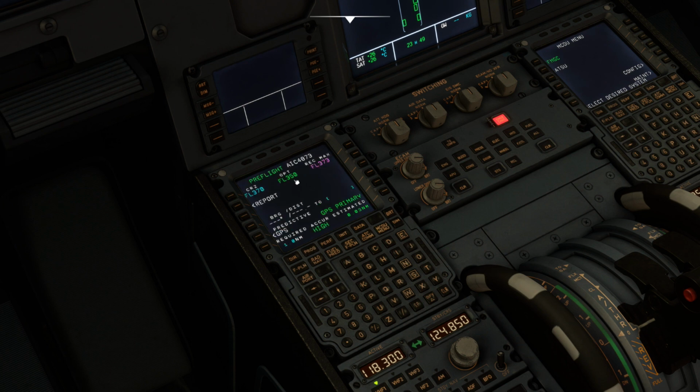Program, our optimum flight level is 350. Our maximum we can go is 373. I will go with the optimum, so I will change my cruising level to flight level 350. Go back over here, flight level 350, yeah. So our flight should be around 1 hour 13 minutes, slightly more after we put in our arrival details.